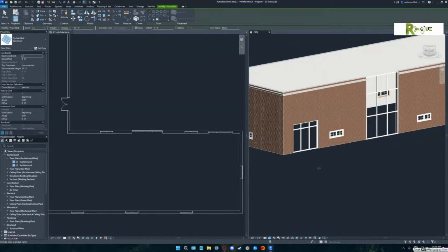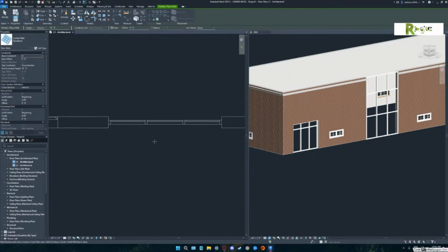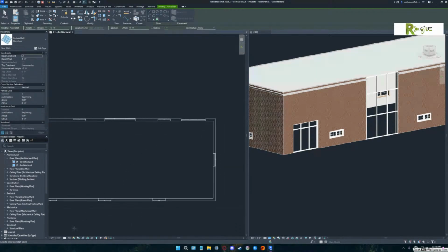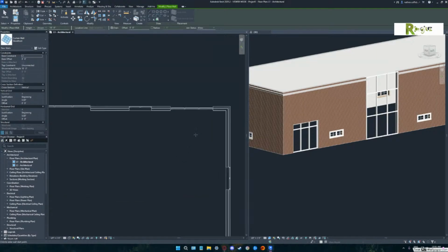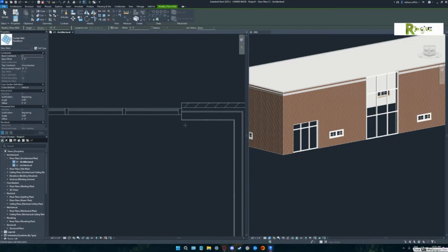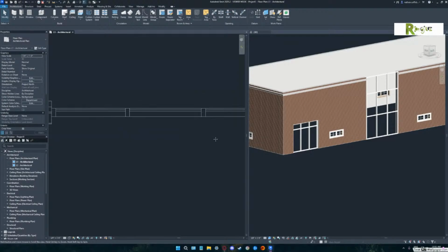And if you zoomed in on plan view, you would find it actually looks relatively good. Now, one of the things is you're in plan view in simple mode. Let's change that to more detailed mode, right next to the 1/8 of an inch. Change that to fine or medium, both are going to do the same. What's going to happen now is you're going to see that layer of brick. You're going to see that layer of gypboard. You're going to see all those layers and how they end up engaging with that curtain wall. That makes sense? Yeah.